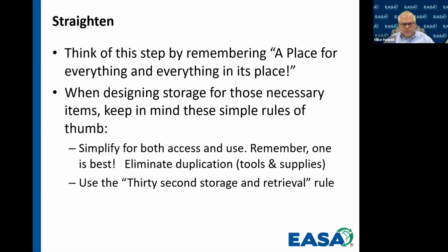And you want to use the 30-second storage and retrieval rule. So if it's a tool you use once or twice a week, you don't want to store it in the bottom of a container behind another container that you need the forklift to move to get to it. You want to be able to go get that tool in 30 seconds or less to be able to use it. And this is a pretty simple concept, but it's sometimes not that easy for organizations to put into practice.